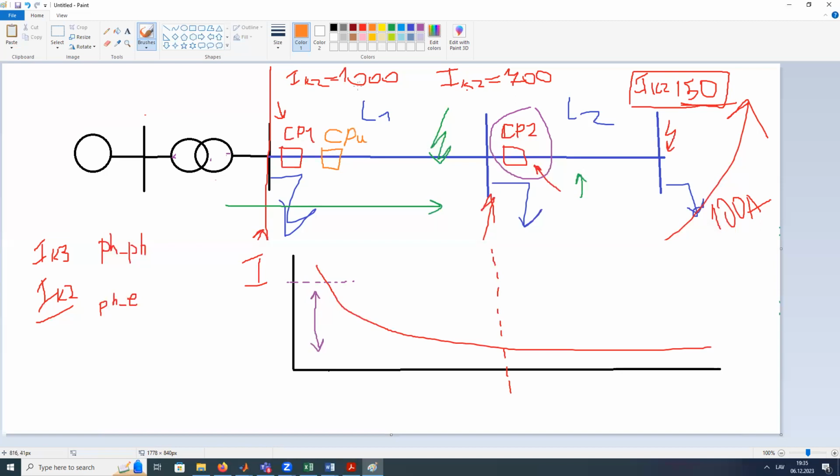Just with the idea, when we have a huge fault current, to disconnect without any time delay. So it has a set point, I say set point 1000, and operates only in case the fault current is high. So it will protect only, for example, this part of the line. Just when we have a very high current value, not to wait and just to disconnect it immediately without time delay. So delta T is 0. So this is the idea of when it is possible and when it is good to use unselective protection in cooperation with a selective protection. Is it clear?